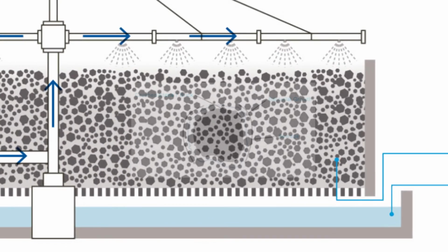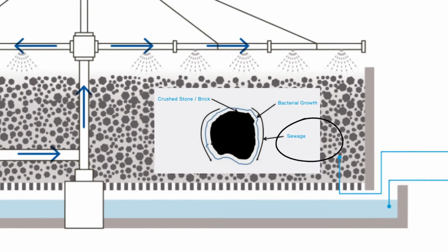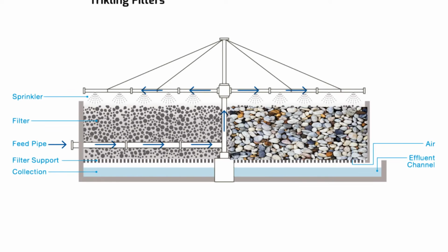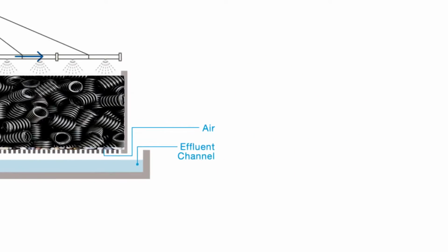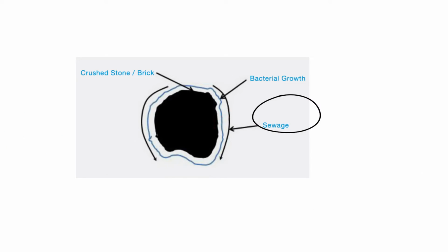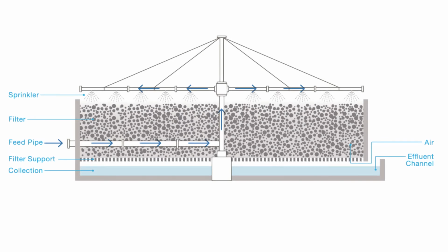Trickling filters are unique biological reactors with a fixed film. They use support media, like stones or plastic materials, to encourage biofilm growth. This biofilm transforms organic substances into carbon dioxide and water while creating new biomass. In a typical design, you'd find a bed of stones, usually 1 to 3 meters deep, through which wastewater flows.